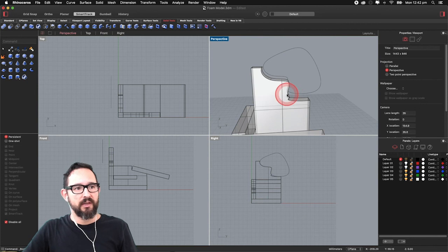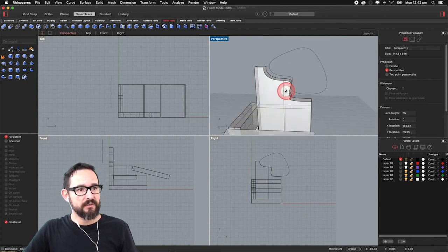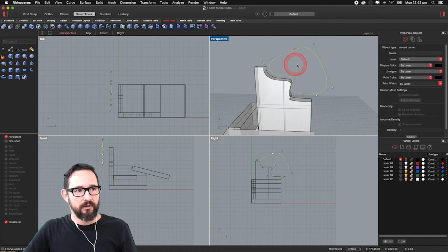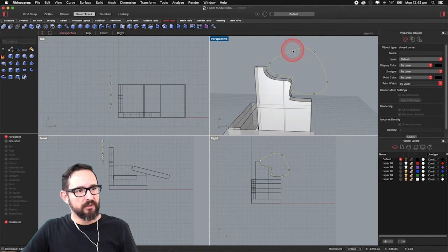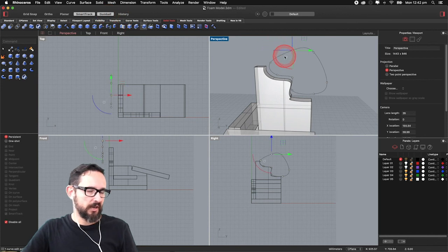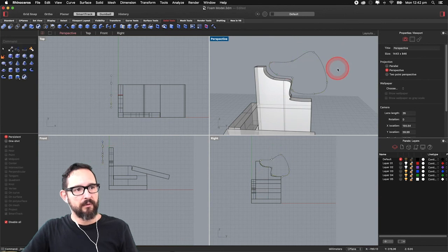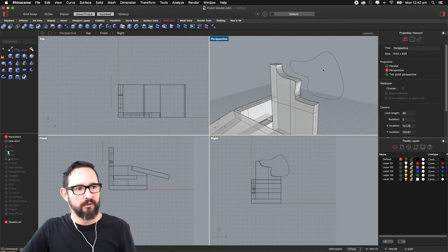If you use solids, it's a different situation. You can actually also use that. In this case, if you don't see these points opening up, the command is edit point on, and then it will show you all the points in the curve actually. All right, and then you can use the gumball to modify, or you can also give coordinates and modify the curve. Once the curve is done, everything is deleted, so you need to redo it if you want to add another form.